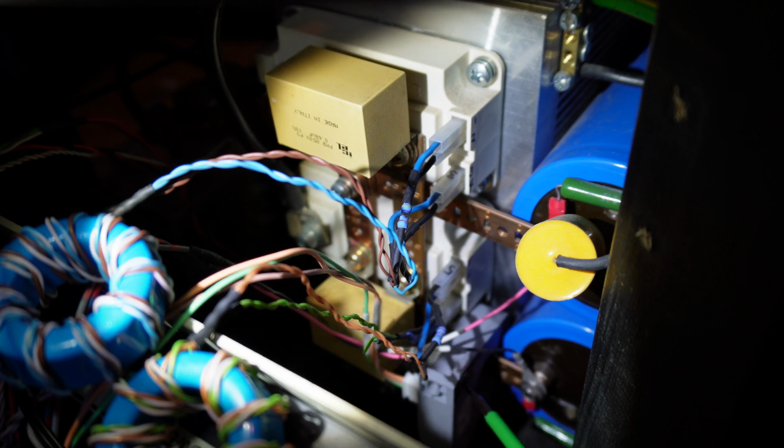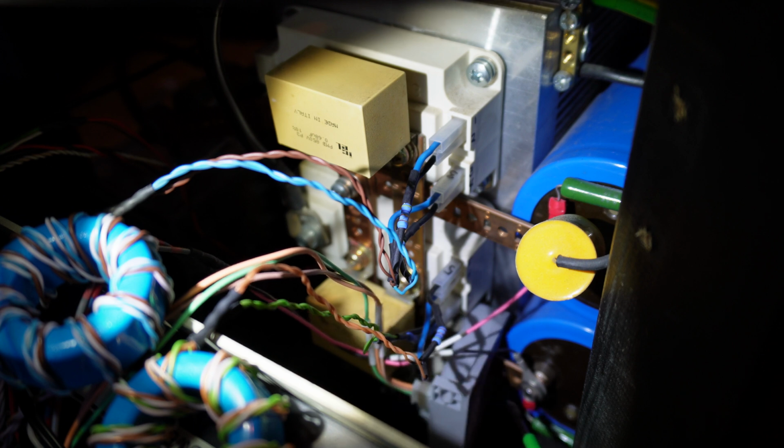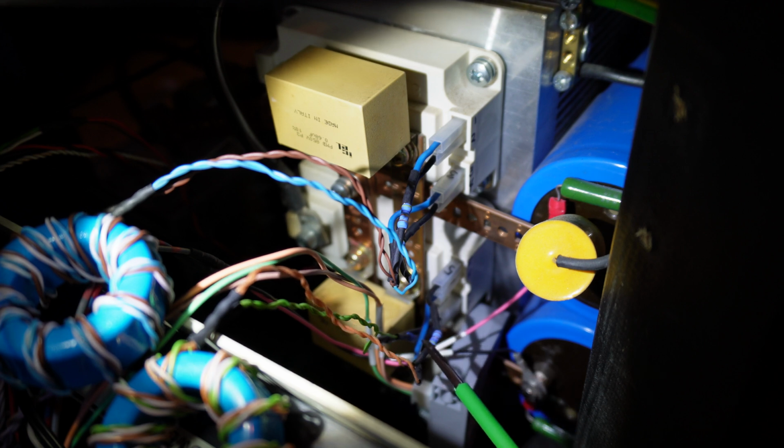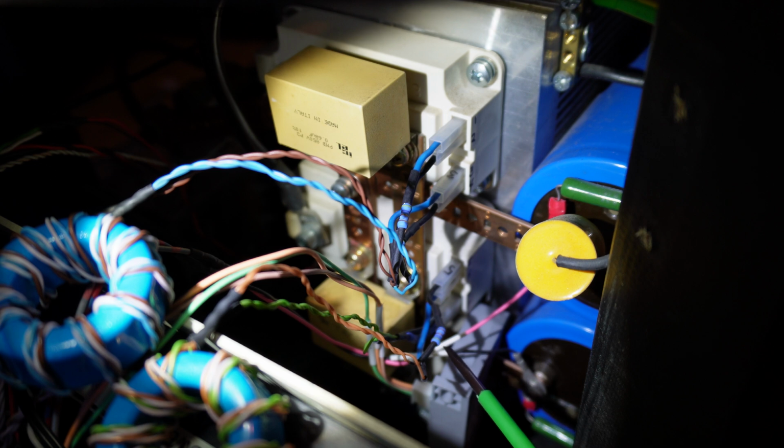The current transformer sits here on the positive bus bar from the DC link. Arrow towards the load, so I hope that's right, else I will have to take all this apart again. The gate drive resistors are 4R7 1 watt metal oxide resistors.